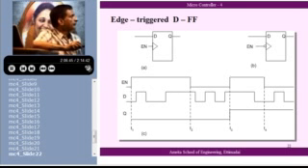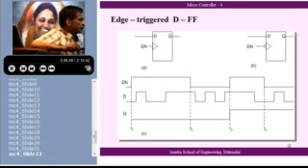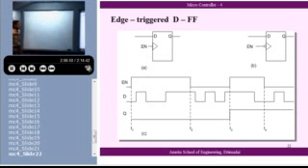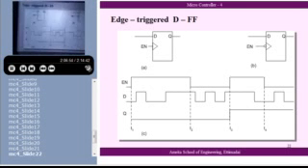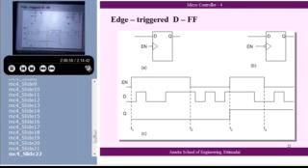You see here. This is the EN value. It has sensed it here. D is high. I don't know where it has sensed. Okay. I'm sorry, it's a positive edge triggered flip-flop, hopefully. So at this positive edge, the D value is 0. It senses and retains as Q. Thereafter D is changing. It is going here, up, down, up, down. D is trying its best to change. The flip-flop says, no, I will not take this. I will remain at this value.